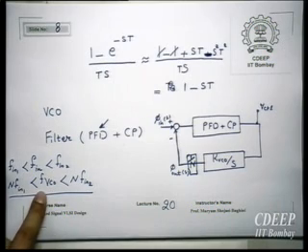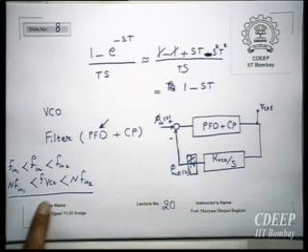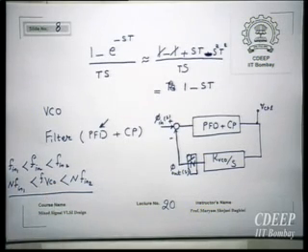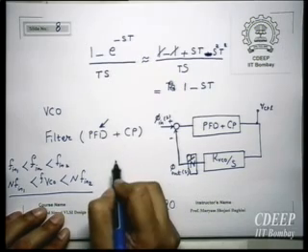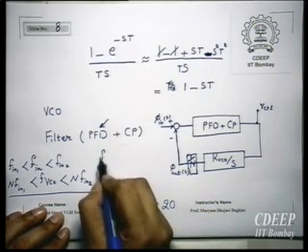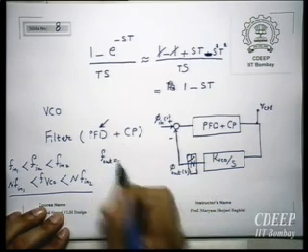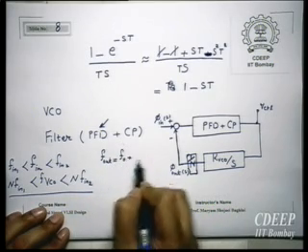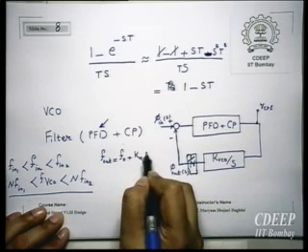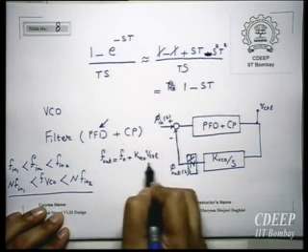And therefore, effectively, I should have a very high speed VCO. If I have a completely linear VCO, I can keep the center frequency of the VCO at the average of these two and then design this VCO. Because now I know exactly what should be the performance of my VCO. Because now F out will be center frequency plus KVCO times VCTL.